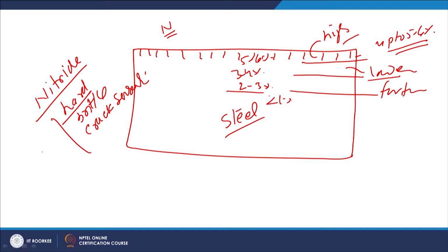Although hardness reduces the friction coefficient, the increased sensitivity to cracking increases the chances of fracture through the growth of cracks. Once cracks are developed, they act as stress concentrators or stress triggers, thereby degrading the mechanical performance of the component.